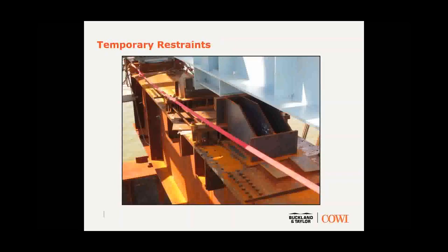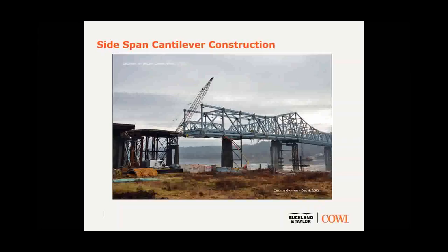One of the aspects of the bearings on these trusses was that they were sliding free in all directions, and the permanent restraints for longitudinal and transverse loading, primarily wind, were separated. So there's wind shoes at the center of the pier floor beams with wind restraints on those, and at the very middle pier there's a set of longitudinal restraints. So here you can see the temporary restraints obviously had to be installed in order to use the bridge in its temporary place, pardon me, under traffic loading.